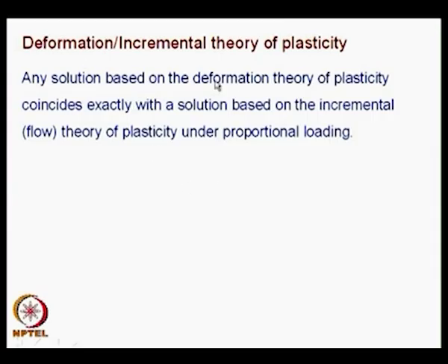I think before we go to proportional loading, we have to justify why we want to go for proportional loading. In the plasticity theory, you have two aspects, one is a deformation theory of plasticity and another one is an incremental theory of plasticity. The deformation theory of plasticity is easy to handle because the mathematics is far simpler, whereas in incremental theory of plasticity, the mathematics is very complex and highly involved.